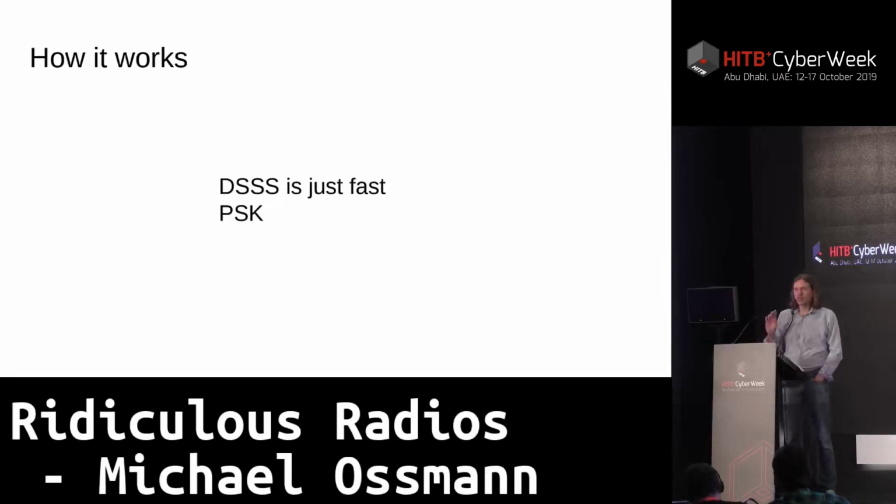What we decided to do was implement a phase shift keyed transmitter in the 2.4 gigahertz band. And there happens to be a very famous thing that operates in the 2.4 gigahertz band that is phase shift keyed, and it's Wi-Fi. A lot of people don't even realize that 802.11 uses phase shift keying because they hear about all these more sophisticated modulations that 802.11 uses. But what it really uses most of the time when it's transmitting management frames like beacons, probe requests and probe responses, those things that are essential for the operation of every Wi-Fi network, is a modulation called DSSS, direct sequence spread spectrum.